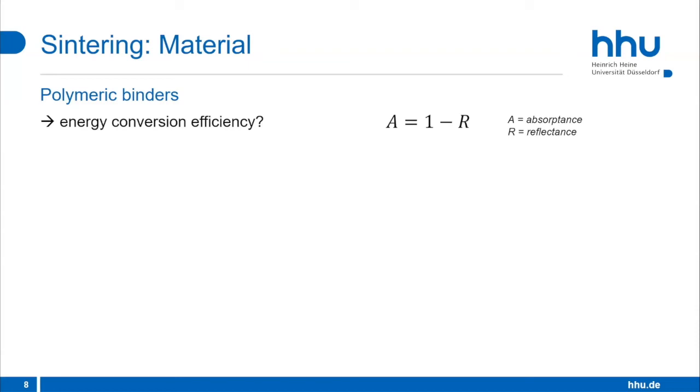And the absorptance depends on the wavelength of the laser, the material that you irradiate with it, the morphology of the particles, the temperature, the gas in the environment, and so on. So there are quite a few ways how you can tweak and optimize your absorptance.